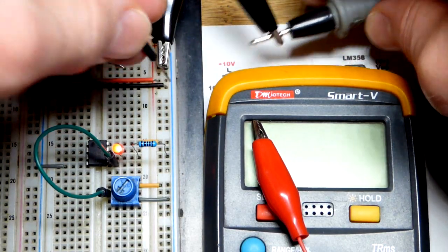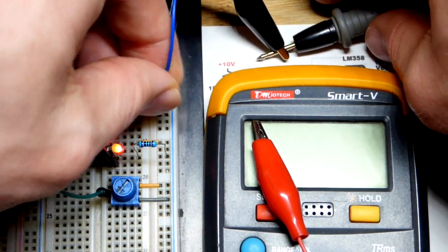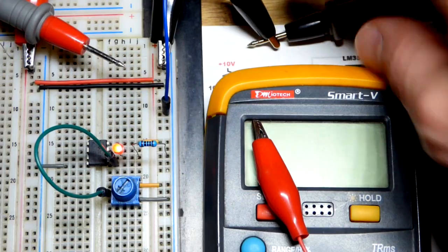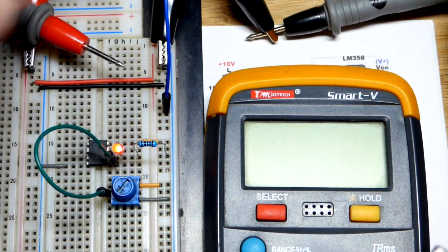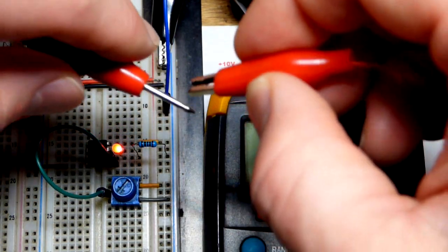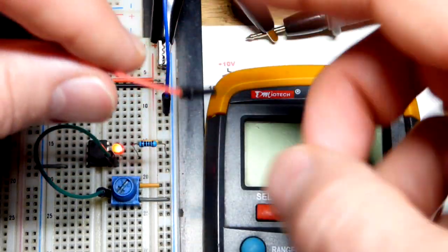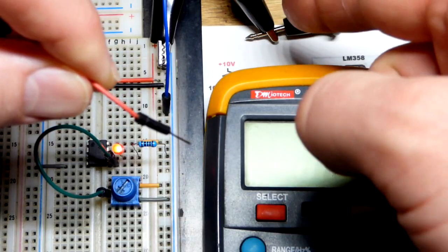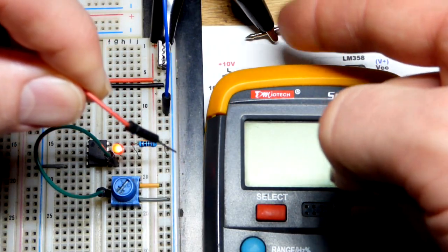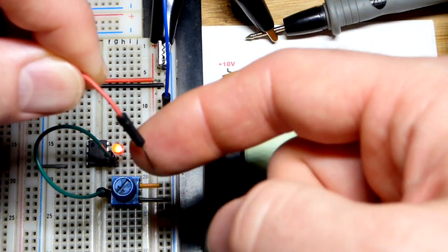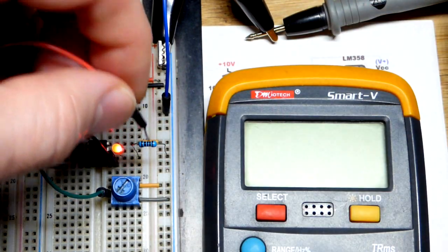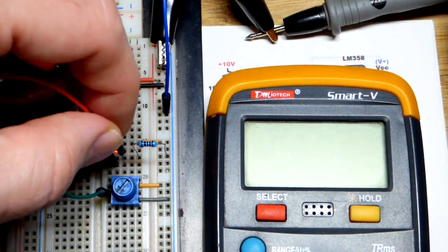So yeah, that's it. I clamp it onto the multimeter probe right there, and then I can plug it into the negative supply because that's the black one that's common, and the voltage we're going to see on display is this voltage in relationship to that one. So that's 0 volts. If we get 5 volts across here in relationship to ground, then it'll say 5 volts.